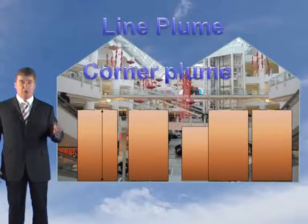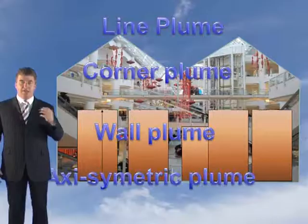Then you've got to decide which model of simple plume. Is it a line plume? Is it a corner plume? Wall plume or an axisymmetric plume? Well, because we don't know, it could be anywhere, the stores could be in there, you must assume it's an axisymmetric plume, and the reason is this will give you the greatest mass flow rate. So therefore, in this case, we're going to use an axisymmetric simple plume.